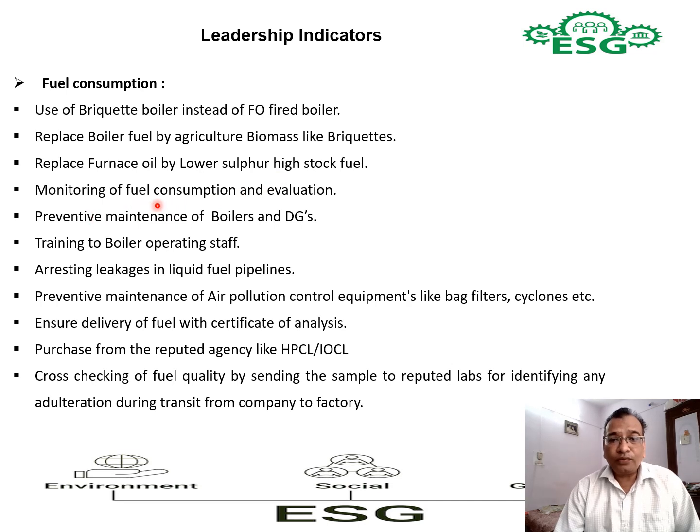Then monitoring of the fuel consumption and evaluation. As I have said, the online electrical consumption is being monitored. Similarly for fuel consumption, there are flow meters and various instrumentation available where you can precisely and minutely monitor the fuel consumption. Once you monitor, you can evaluate, you can trend, and you can see whether the fuel consumption is increasing or it is the same.